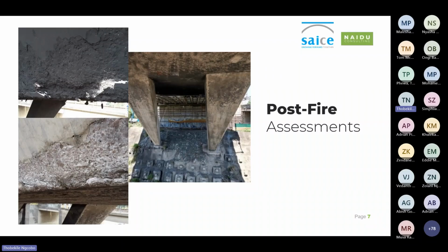In this project, we used these methods selectively and strategically, extracting only a small number of cores, for example, from representative areas to confirm our observations, rather than relying on them exclusively. So this balanced approach ensured that destructive testing served its most important role, which is verification. It allowed us to confirm the data obtained from non-destructive techniques without unnecessary material loss.